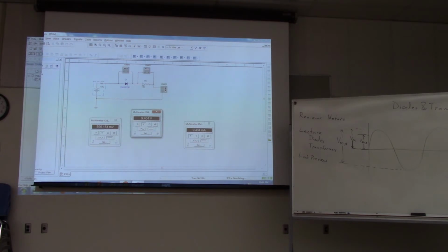There's not a number that you can just add up like you would add up resistors in series. Basically, you deal with diodes differently when you are calculating the voltage and current in a circuit. With a diode, you treat it like a voltage drop rather than a resistance.